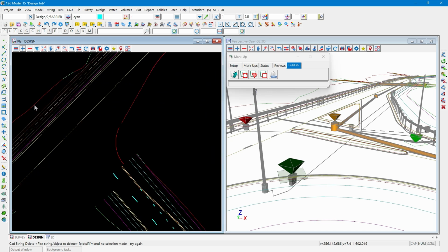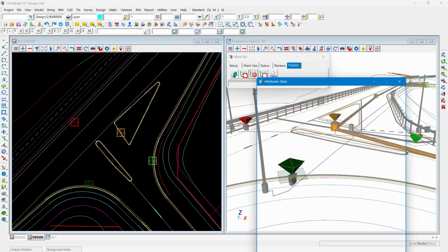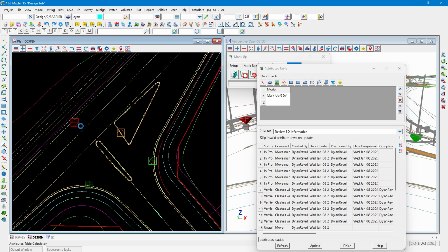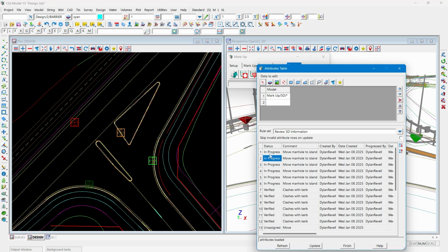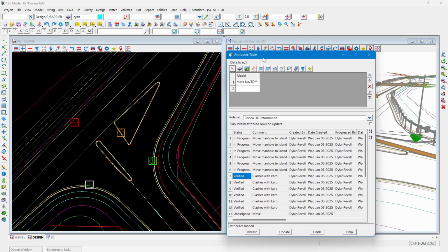When we look at the 3D review table and hit refresh, the reason we went with both a tri-mesh and a rectangle for each of those 3D reviews is that when you want to highlight and zoom around these, it will do so on the rectangle as opposed to the pyramid or the tri-mesh. So you'll see as I place through there, it is highlighting those rectangles themselves, verified ones. You can sort the table, and it's a very handy feature if you want a global snapshot view of where all the status of the markups and the reviews are.